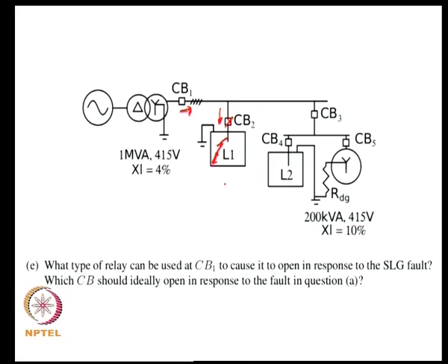So, you have a possibility that you might have a load, and because your breaker may not be equipped to measure residual current, you might stay with the fault for a longer duration and cause potentially overheating of conductors, etc. So, you have to look at what your specific rating is, what your fault current is, and ensure that you have protection against overheating or sustained long term operation under faults.